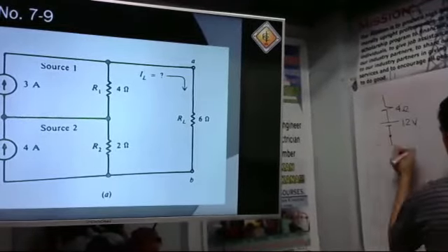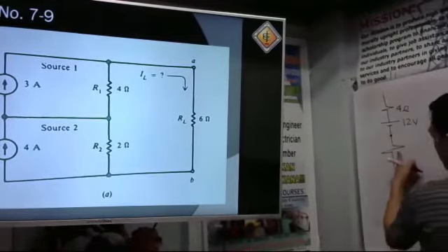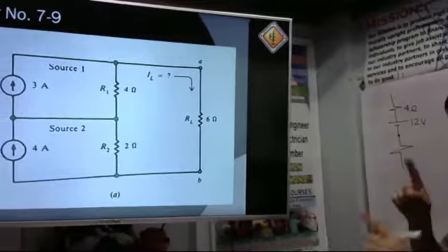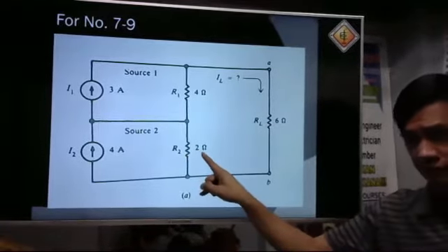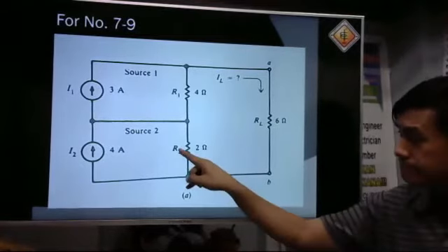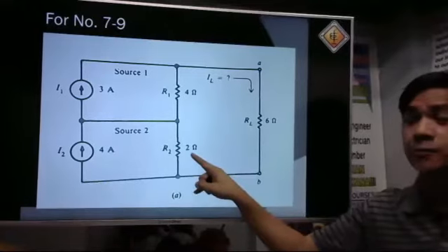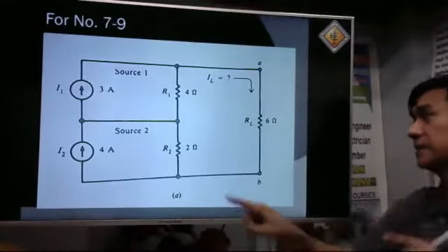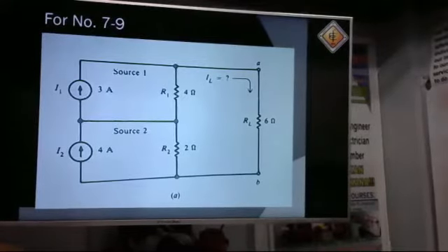let us have the resistance again here. What is the value of this resistance? Just copy this 2 ohm resistor. This is the Norton's resistance. That is just equivalent to the Thevenin's resistance. So I will just copy these 2 ohms. So put here 2 ohms.